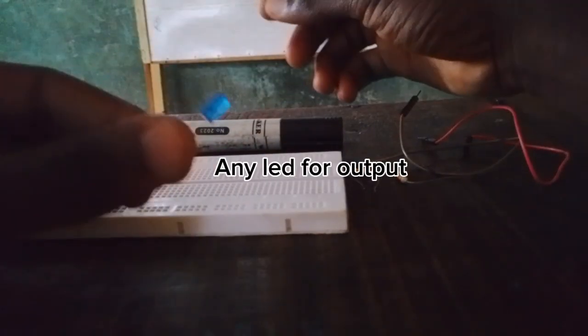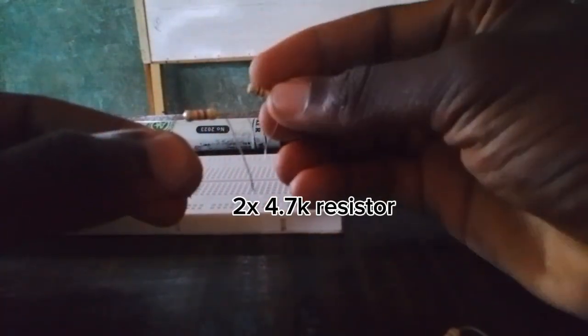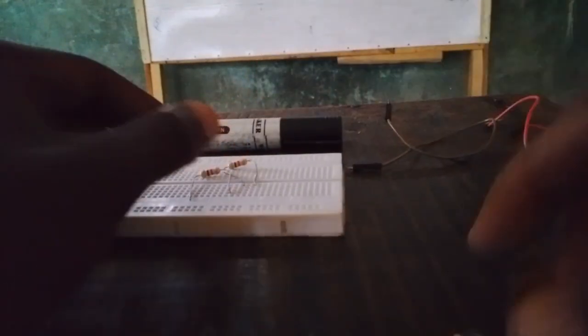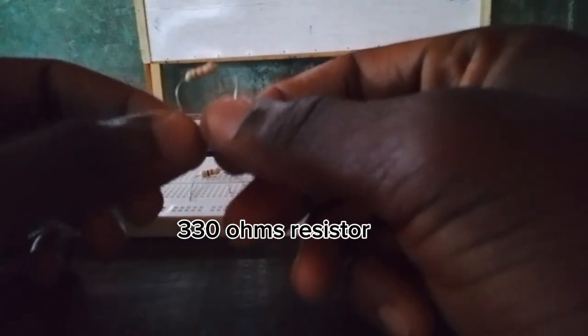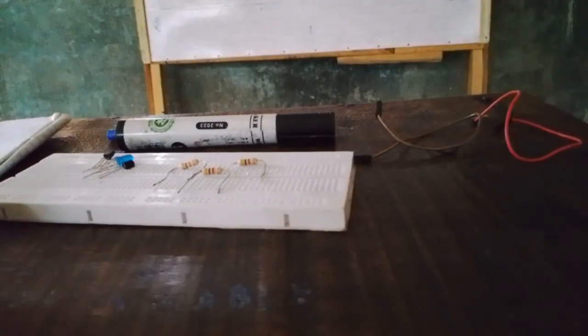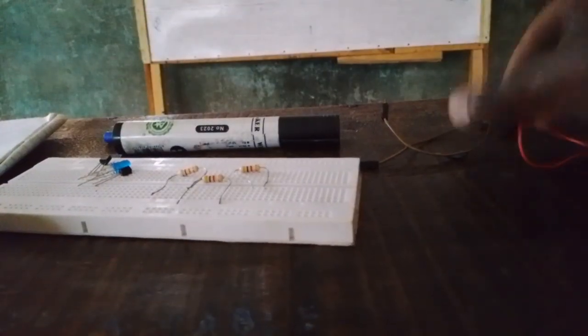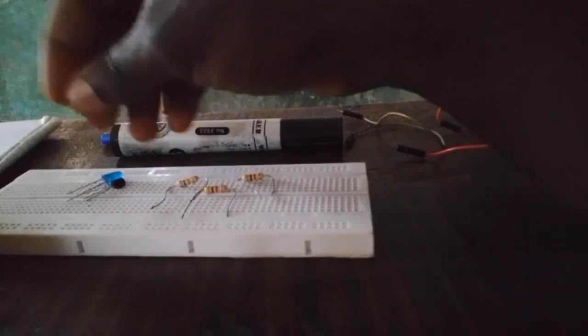You need one LED as your output. You need two 4.7 kilo ohm resistors, or you can use 1 kilo ohms, but in my video I'm using 4.7 kilo ohms. You need one 330 ohm resistor, your breadboard, your power supply, and your jumper wires for your input. Now let's build it from scratch.